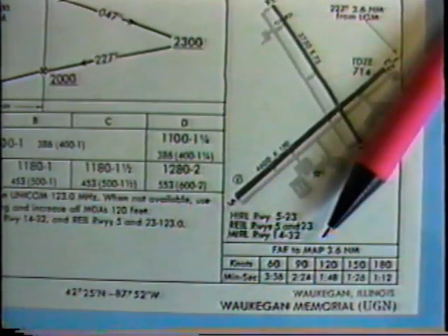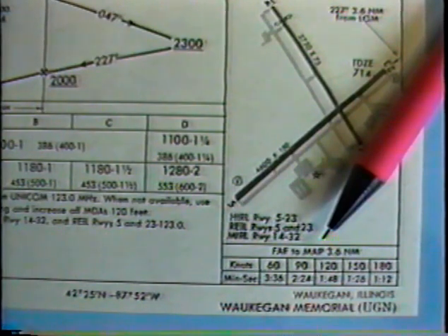In the event that a glide slope receiver fails or the glide slope is out of service, the pilot can make a localizer approach by referring to the time and ground speed box and timing from the final approach fix.